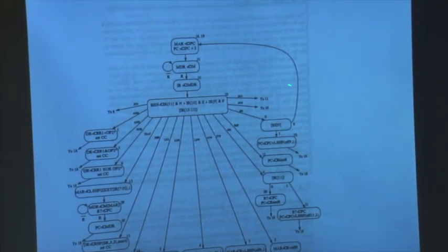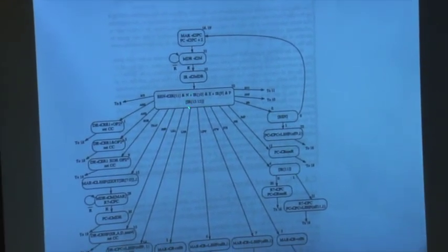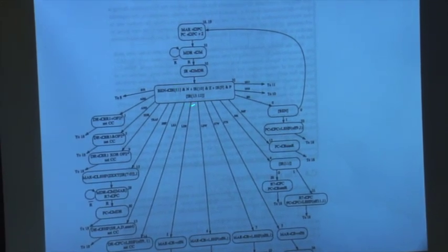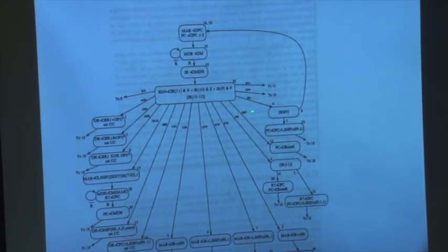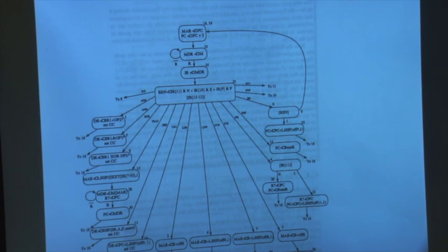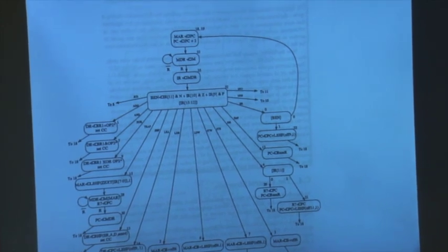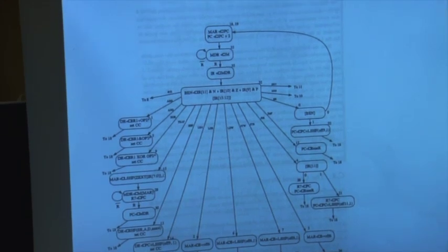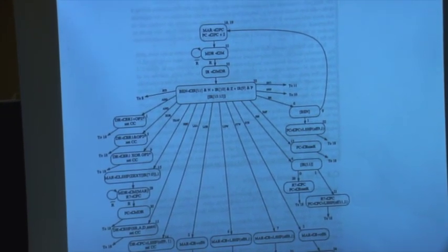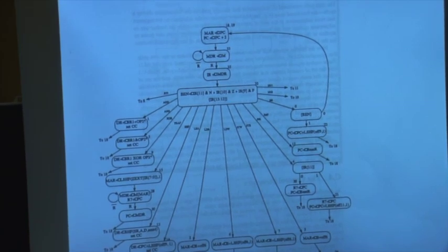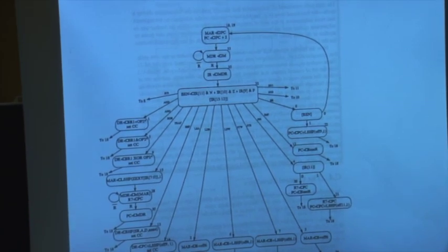But here, this is the state. So you figured out your instruction is a branch. So in this state, the next state is the state that executes the branch instruction. And there's a branch enable signal that was pre-computed in the previous state. It happens to be, according to the specification, and if you look at the LC3B ISA, the branch computation is based on condition codes. You guys know what condition codes are? Yes? Some of you do.